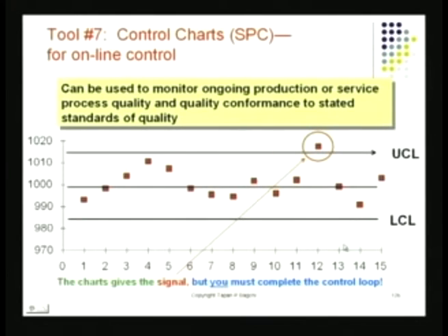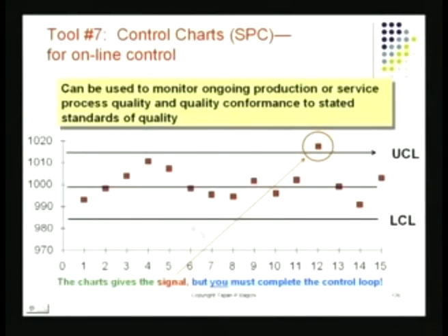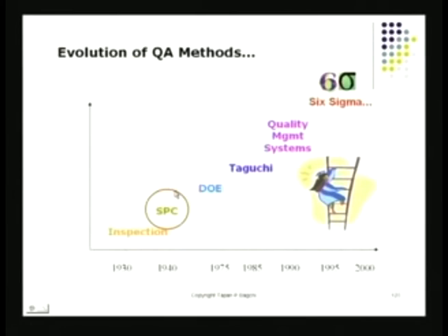Then this last chart is called the control chart. This is the SPC, Statistical Process Control chart. This I'm going to be discussing in great detail when I discuss SPC with you. But it's a way to try to remember two things we mentioned. We mentioned the issue of accuracy, and also the issue of precision. In a general manufacturing process, both of these could be problems. I could have problems of accuracy. I could also have problems of precision. Both of these can be kept in control by use of the control chart. The control chart itself becomes the greatest tool for doing this. There are two types of charts used here, the X bar chart and the R chart. I'm going to be giving you details on them.